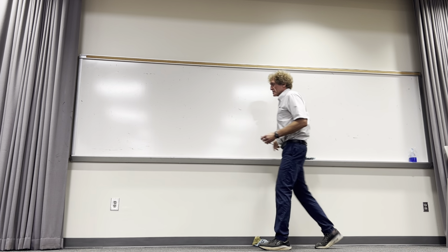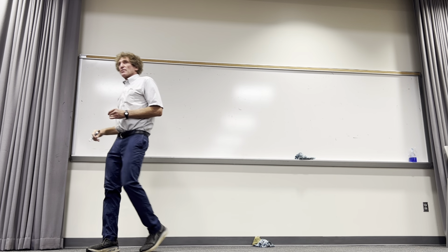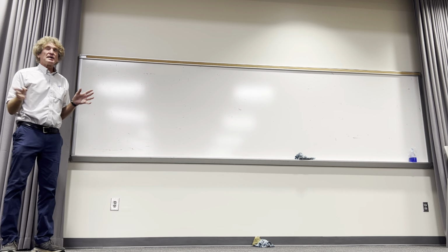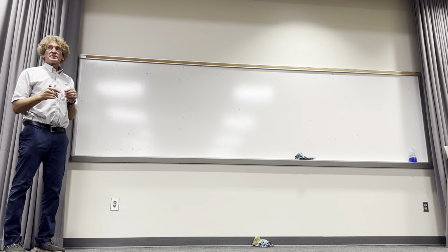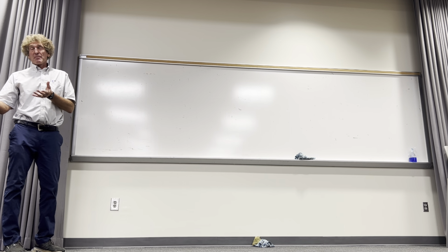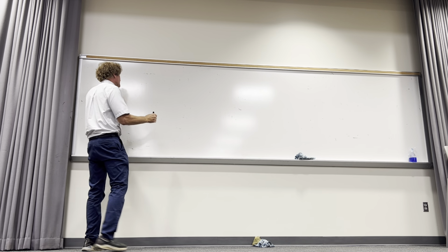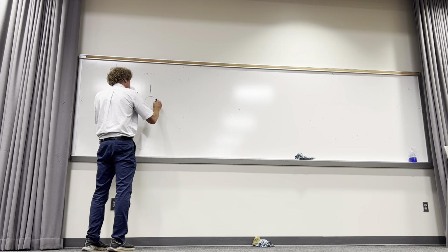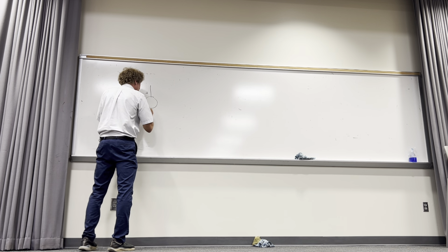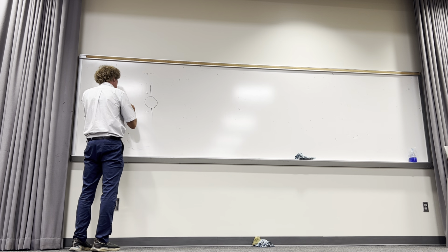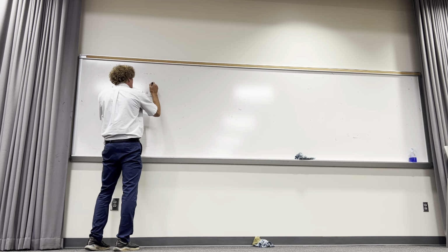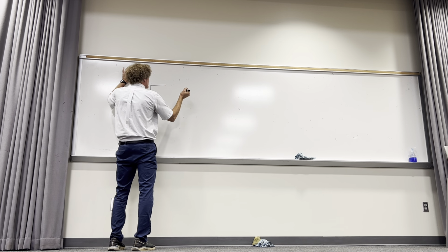And here's what it amounts to. What they're going to do, any system in the world, any electrical system that's a linear time invariant system, a power supply, a battery's charged, something like this, can always be represented by a single voltage. Here, this would be the Thevenin equivalent or open circuit voltage, but I'm just going to call this some source voltage right here, and it will have some impedance right here.